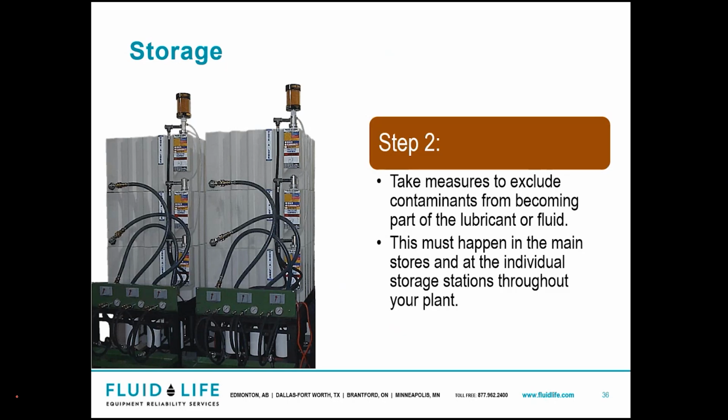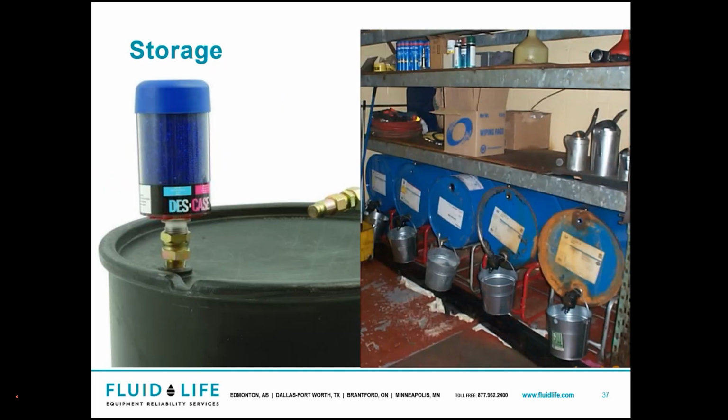Dragging around a filter cart, I know that can be a pain in the butt, but filter carts are one of your best friends when it comes to adding oil on site, and we'll touch on that in a couple of minutes here. When it comes to storage, desiccant breathers and quick connects are all going to be good things.